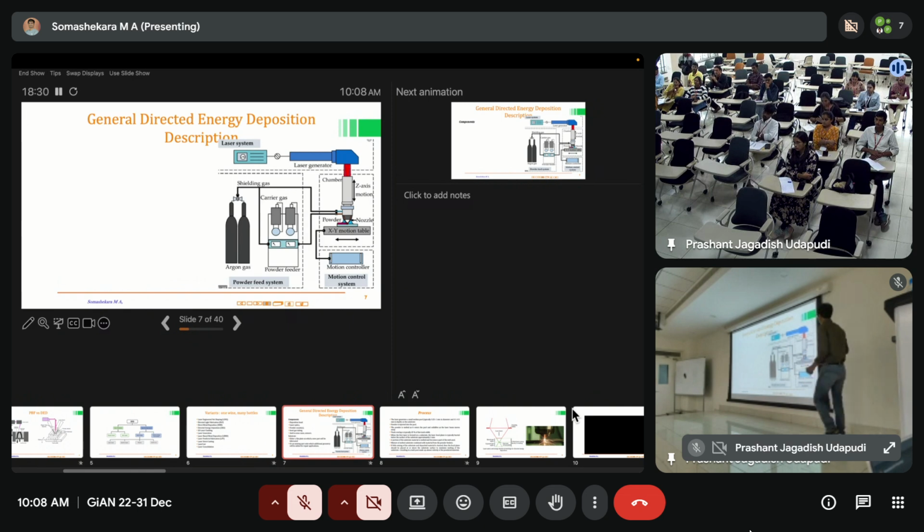But most of the time you will see that the head, which is called a print head, is mounted on a z-axis motion, so that you can avoid too many motions within the system. When you have this kind of mechanism, it also helps in managing your speed, etc. Most of the time you will see an x and y motion table used as the base plate, where you deposit on top of x and y, and you move as per the CAD file.